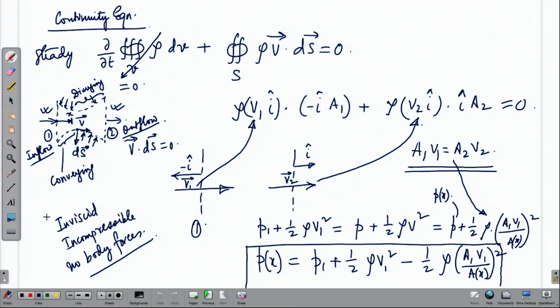So, that is how we could first work out how the continuity equation looks across the inlet and the outlet of that duct. Basically, we can apply this law to any station along the length of the duct, and additionally we looked at how along the length of the duct the pressure would vary and how we can work it out by combining the continuity equation with Bernoulli's equation.